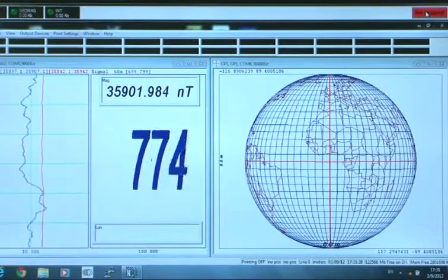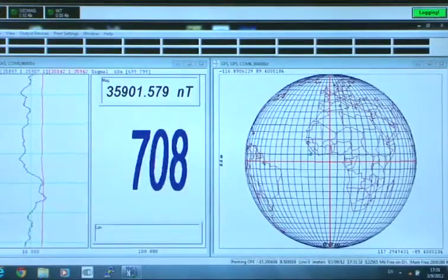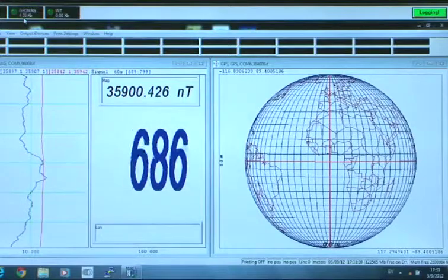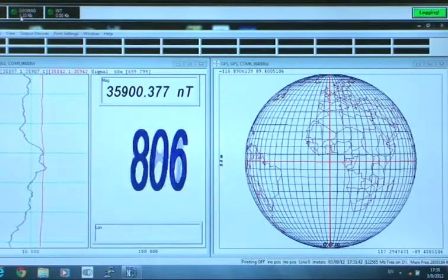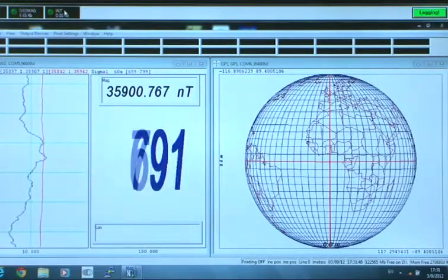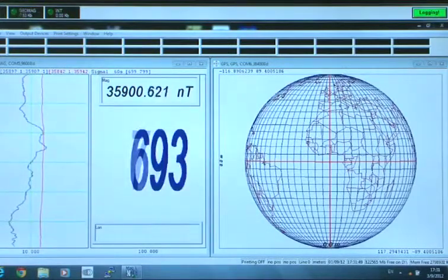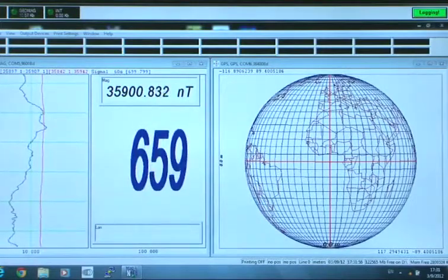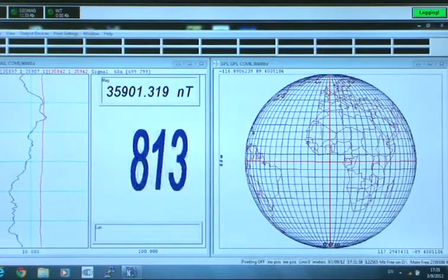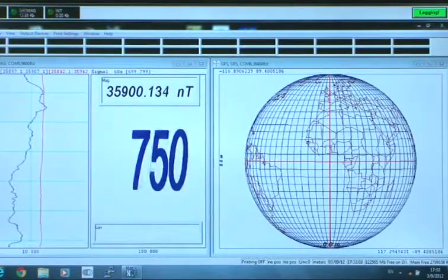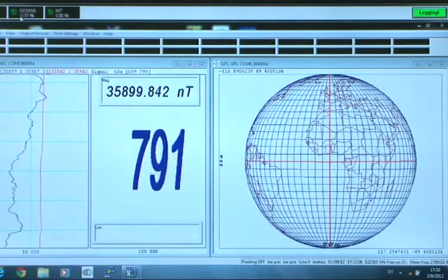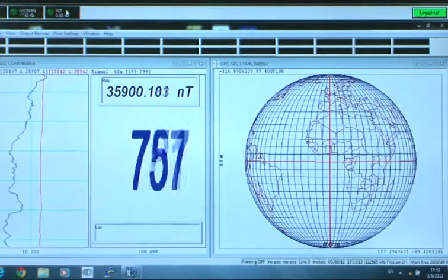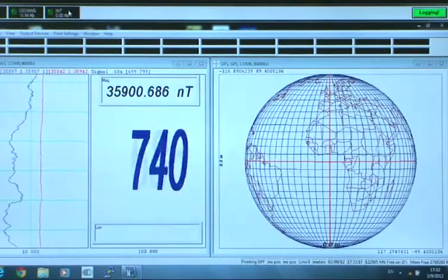When we start logging, data that is available will be logged to hard drive. Data that is being logged to hard drive will show as incremental numbers in the status windows for each device. In this case, the GPS is incrementing, showing that there's some data being stored for GPS, even though we have a warning condition for GPS. And magnetometer is showing data being recorded. INT is a device for the interpolator. The interpolator will not function without a fix, and so there is no data being recorded by the interpolator.